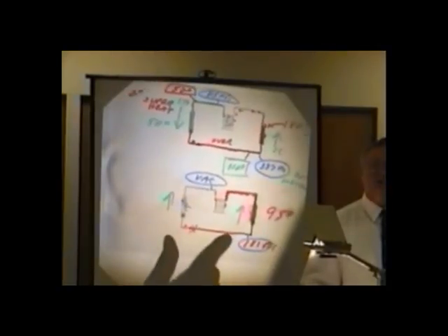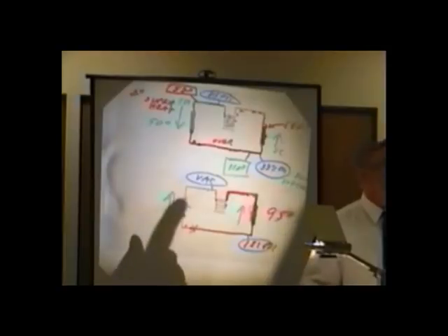Over here on an undercharge, we starve the evaporator. On a restriction, we're starving the evaporator. So the clue to a restriction is up, up. Now go to your handout and find that page. You're going to love it. It's on page 4.